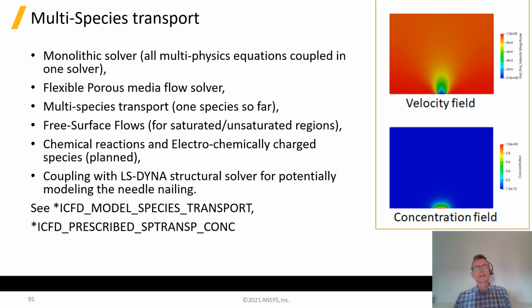So multi-species transport has been added. That means other substances being carried along with the fluid. So the initial application driving this is quite a surprising one. It's another medical application, and it's fluid structure simulations of intradermic injections, so like your COVID jab. So they've been adding a transport model coupled with fluid structure interaction.